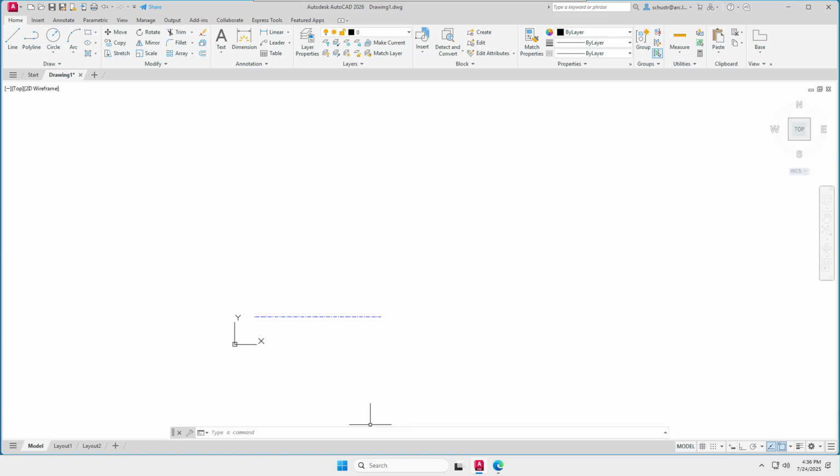Okay, and down at the bottom I have something called the command line. You can move that around, but I'm going to do a line, and down here it's telling me where are you going to start. I'm going to start there, and then it says where are you going to go, and I don't care where you put it. It can go anywhere because I'm going to type on the bottom, and I start with an at. I'm starting from where I'm at. See how it came up on the command line. 115.1.